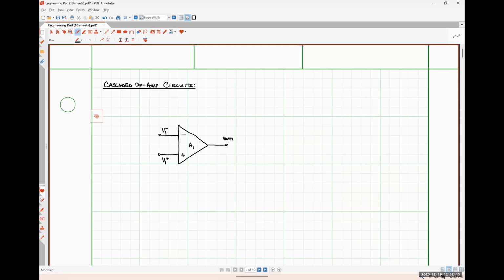Now I'm going to draw the remainder of the circuit, including my feedback path and all of that kind of good stuff. So let's say that I have a 5 kilo ohm resistor here. Maybe a 10 kilo ohm resistor here. And this leg over here is where I'm going to apply my input signal, Vin of t. And I'm going to ground this guy, like so.